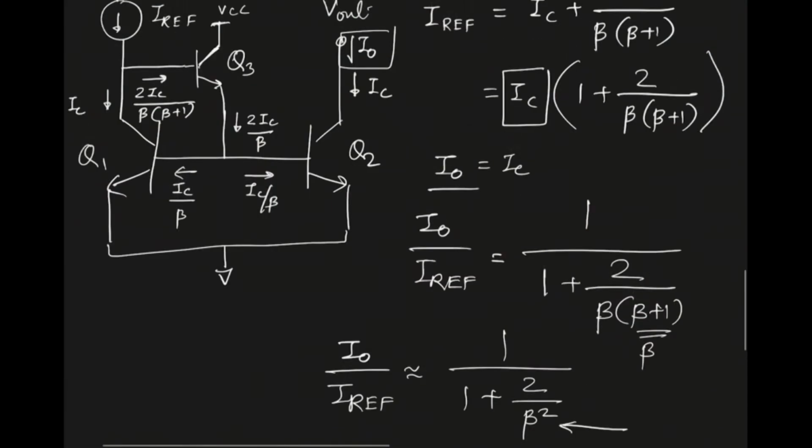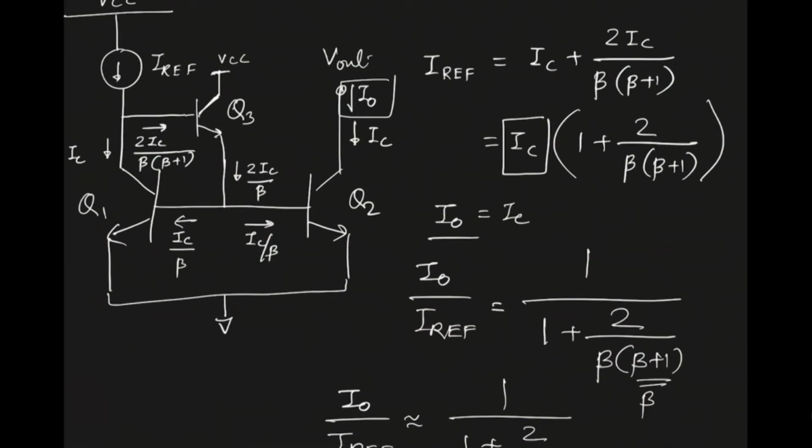So this particular current mirror doesn't improve your output resistance, right? You don't have a cascode here, because if you do a cascode, then you still have to worry about the base current. In case of the MOSFET, we don't have to worry about the base current. So we could just do cascoding and increase your output resistance as much as you like, and modify some conditions to improve the output voltage swing.